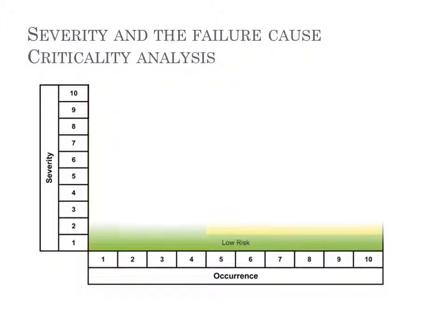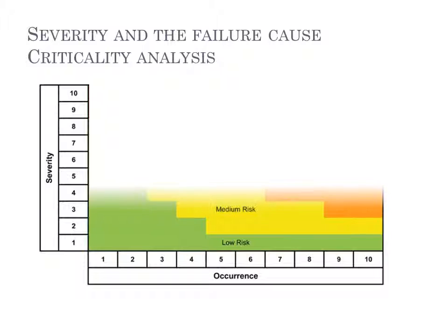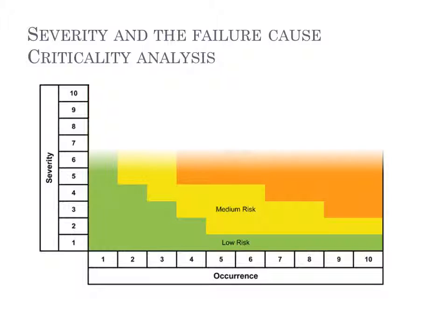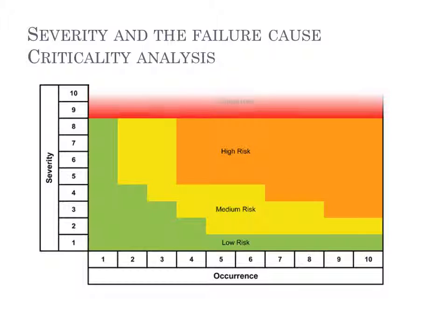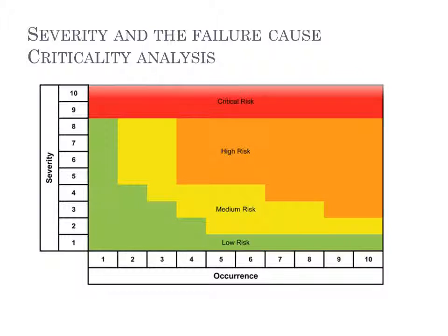To use qualitative criticality analysis to evaluate risk and prioritize corrective actions, the analysis team must first rate the severity of the potential effects of failure and rate the likelihood of occurrence for each potential failure mode. It is then possible to compare failure modes via a criticality matrix, which identifies severity on the horizontal axis and occurrence on the vertical axis.